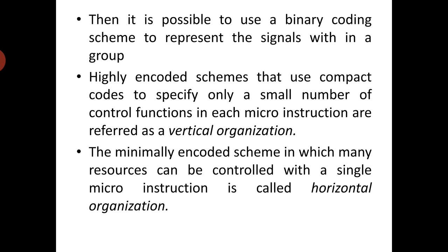Also, the register output control signals can be placed in a group consisting of all the register output signals. Register output signals means PC out, the program counter output control signal, MDR out, the memory data register, Z out, offset out, and R out.